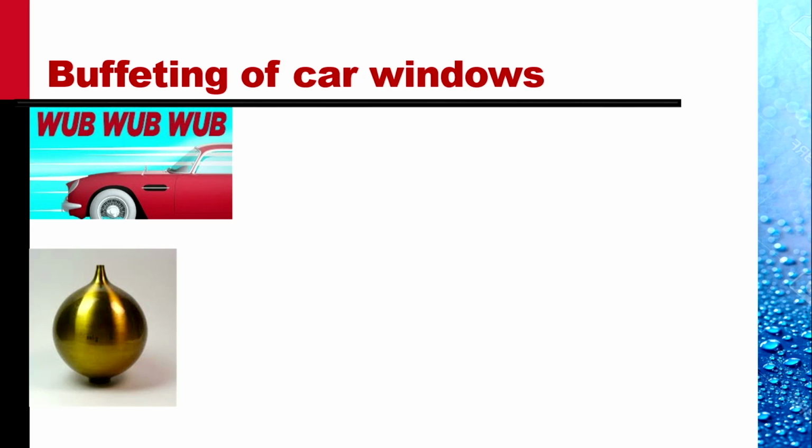The volume serves as a spring and the mass in the neck oscillates. Given a volume and given the neck dimensions, there is a particular frequency at which this resonates. And so you hear that sound.